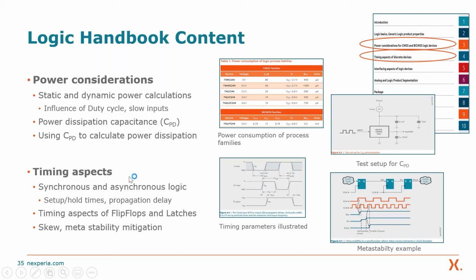Apart from the timing properties of our devices and the general requirements for this, we also cover general timing aspects like skew and metastability, and also recommend what can be done to mitigate metastability. These little figures are examples that I have pasted in from the Logic handbook to illustrate our explanations for the various timing aspects.